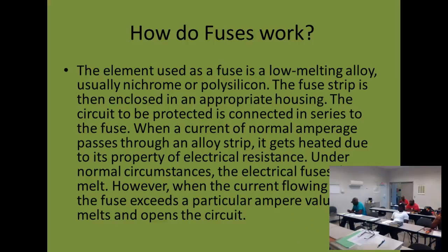You follow me? So I cut the power. That's rule number one on my ohm meter. You read from here to here, and you go, hey, I got resistance. Well, yeah, you didn't isolate. We're actually reading three different circuits. Do I want to read this one? Then isolate it. Do I want to read this one? Yeah, isolate it. Do I want to read this one? Isolate it.